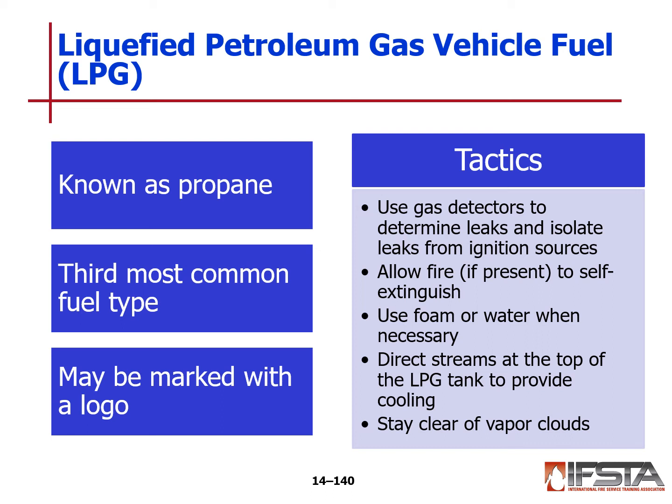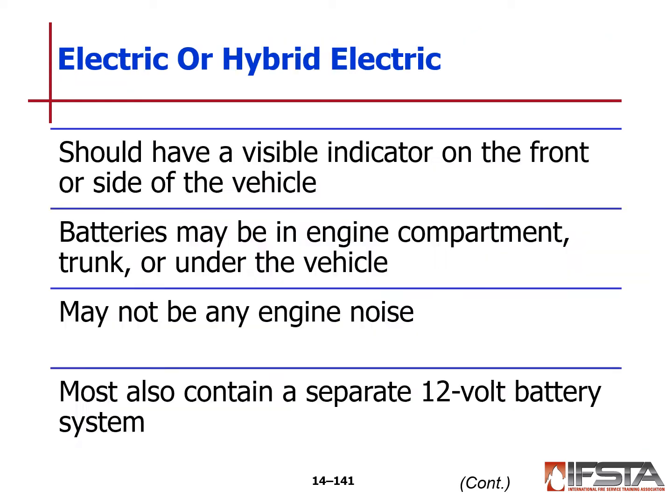As far as detecting the leaks, we use gas detectors to determine and isolate those leaks and ignition. So we want to get rid of any ignition sources, allow the fire, if present, to self-extinguish. You may use foam or water when necessary. Direct our streams at the top of the cylinder and provide cooling of the cylinder to keep an explosion from occurring. Stay clear again of any vapor cloud.